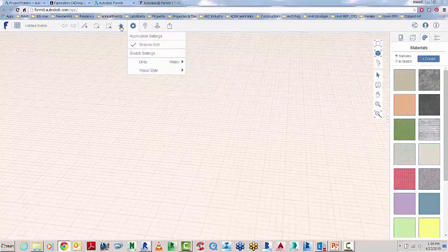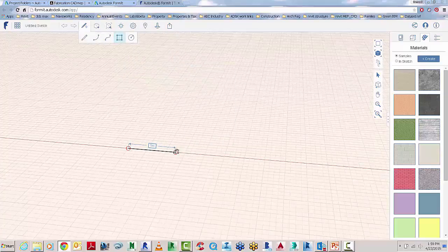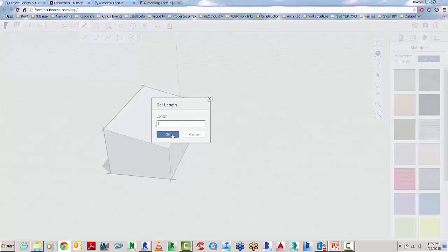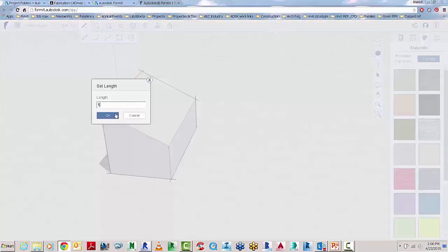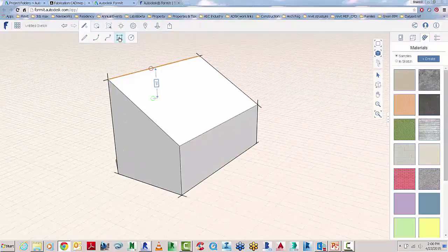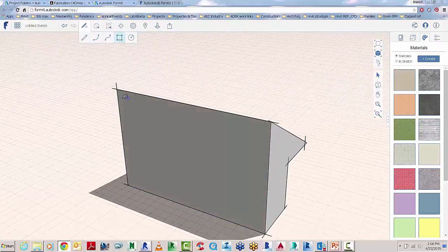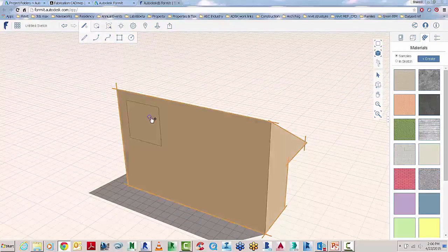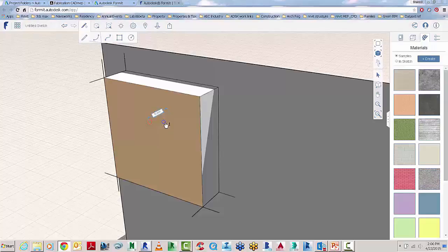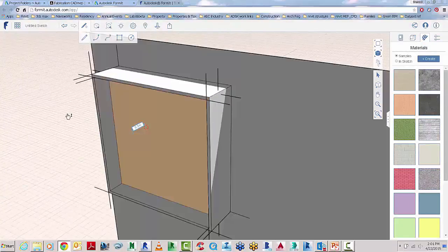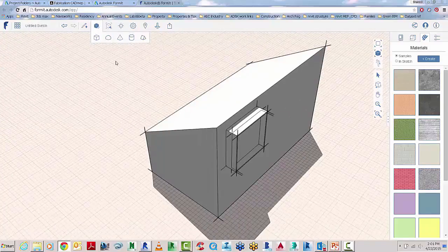So what we're quickly doing here is just turning on our conceptual styles that we want to display the model, also converting it to metric. And Formit is a very simple tool for just doing push-pull modeling. So we can extrude, draw on faces, push-pull components to sculpt the building in the way we want. When we extrude, we can also do offsets on the inside of that face to create a frame for our window.